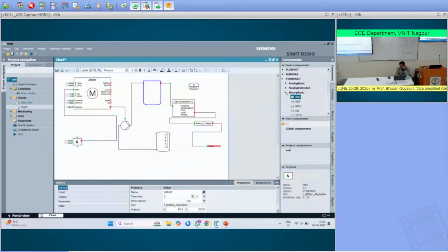Basic programs, conversions, multiplication and compare values can all be done here, because the PLC will send 4 to 20 milliamps. For that we need to convert integer values to analog values. All conversion-oriented things are possible, and basic standard libraries are also there, through which we can convert all the data inside the platform itself.